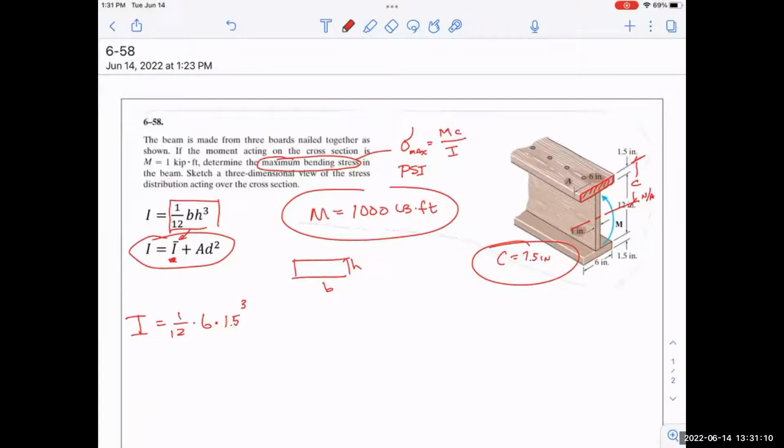But the second part of this is not just how much material is it? Does it make sense to you? This is really important. If I take this beam and go like this on it, that top wants to get shorter. So it would be nice if there's a lot of material up there. But the second thing that's important is where is it? Because if this top piece right here is a lot higher in the air, then it has to get a lot shorter and it doesn't want to. Does it make sense? Something this small is going to want to bend really easy.